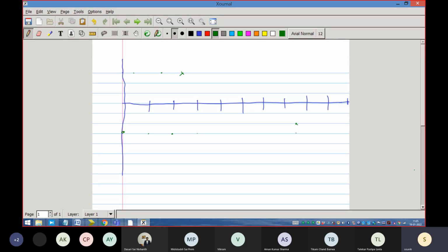Why sawtooth? Why is it not a continuous ramp function? Because we are breaking it in every switching period and recalculating it. We are not calculating one time; we are recalculating the duty ratio. We call it the duty ratio: the on time of the switch with respect to the switching period. After every time period TS, everything has been divided into TS parts: TS, 2TS, 3TS, and so on. We have divided the time, and every time we are calculating.